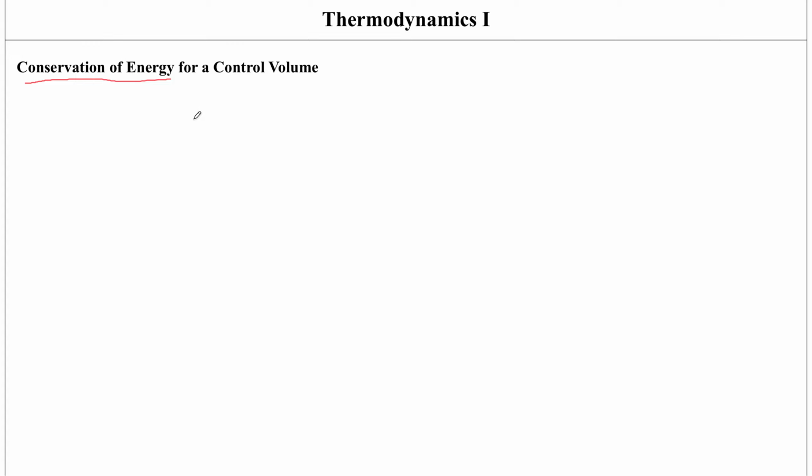One of those concepts was the total energy of a system. The total energy of a simple compressible system that we saw was in terms of internal energy. And this is on a unit mass basis, so that's why it's being represented by small case letters. So it's composed of internal energy plus the kinetic energy, which can be written in terms of half v square, because obviously it's on a unit mass basis, so m is equal to 1 here.